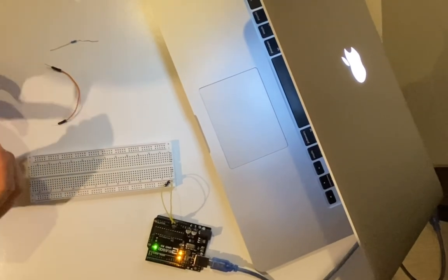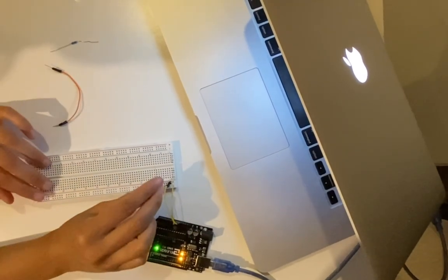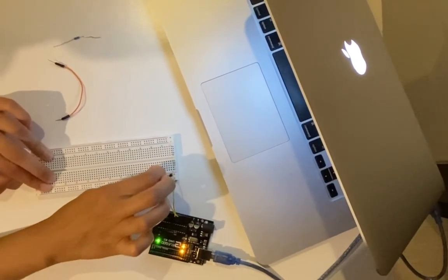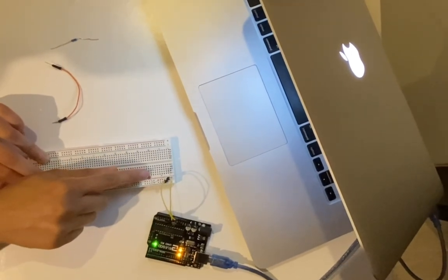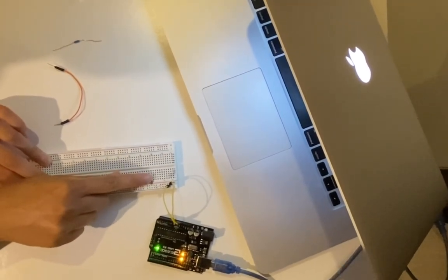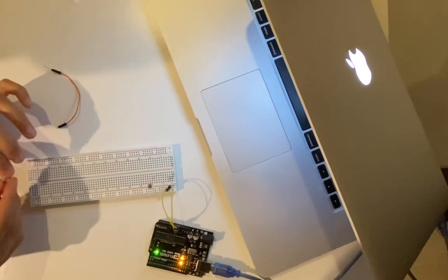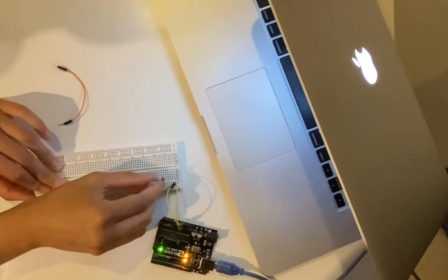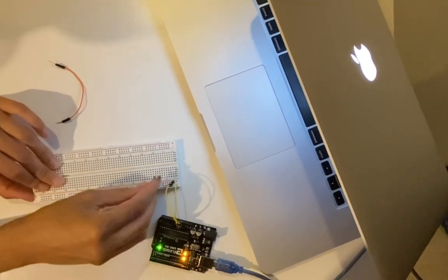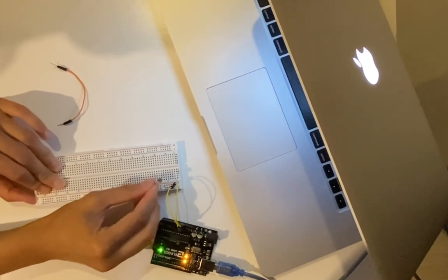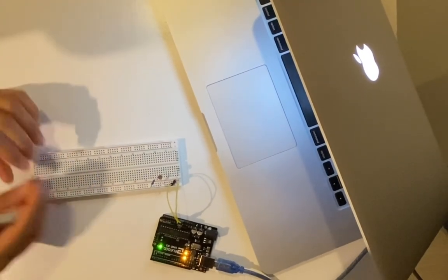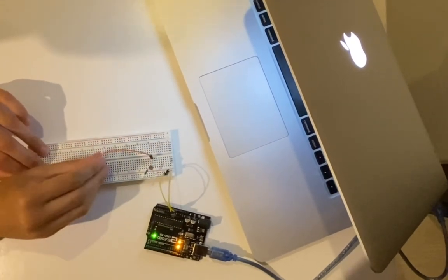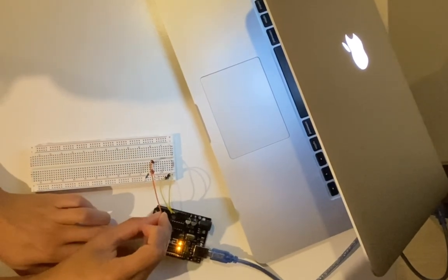If you remember the circuit, the LDR connects to the positive terminal, and on the other end it connects to the resistor. I will pin it to any free connection on the board. At this moment it doesn't matter. In that series of pins side by side, all 5 pins are connected to each other here. The pull-down resistor goes to the same pin and connects to the ground. Now the circuit is complete. The last thing we need to do is connect the output pin where the sensor and the pull-down resistor meet to the A0 analog pin of the controller.